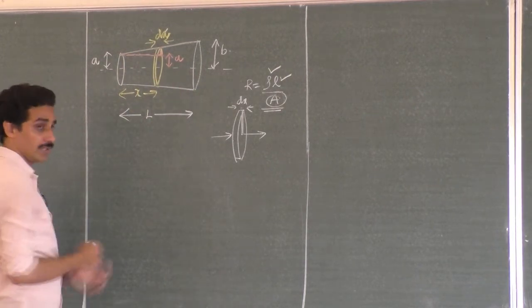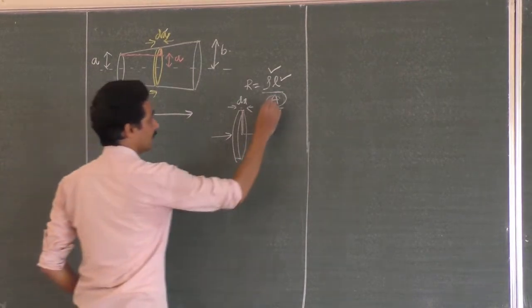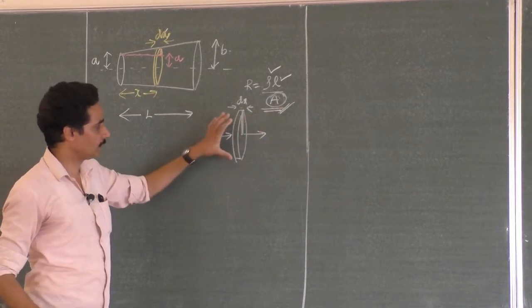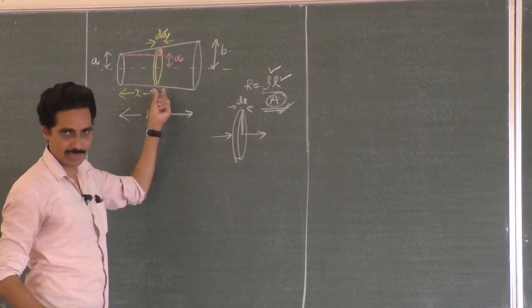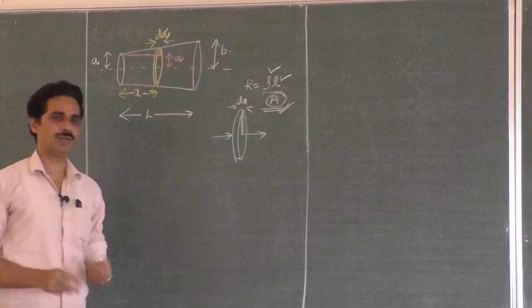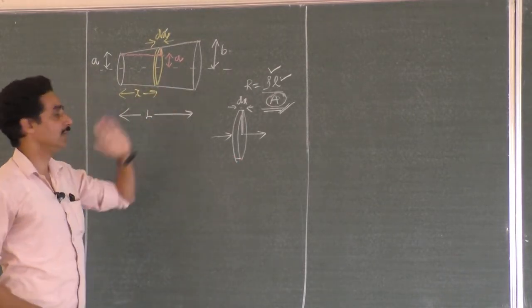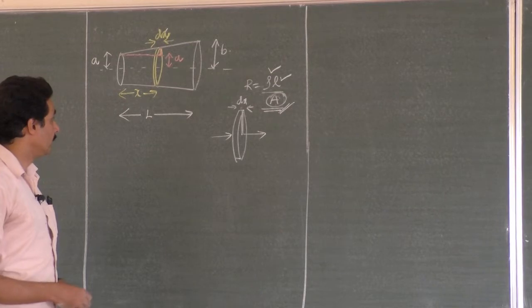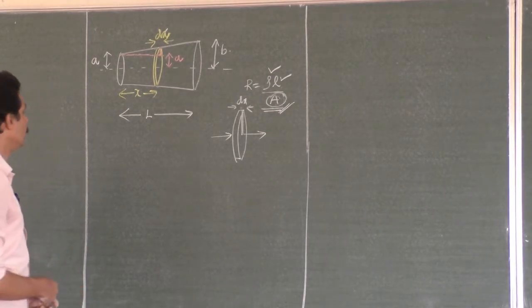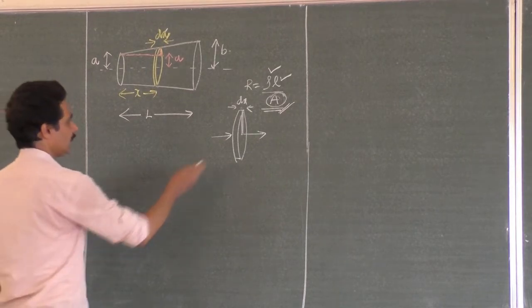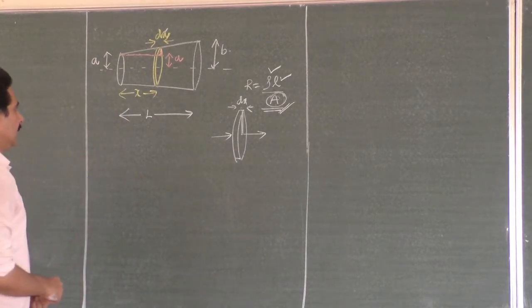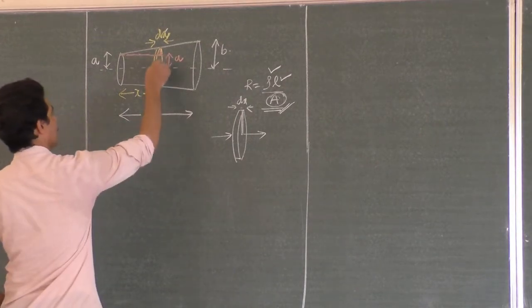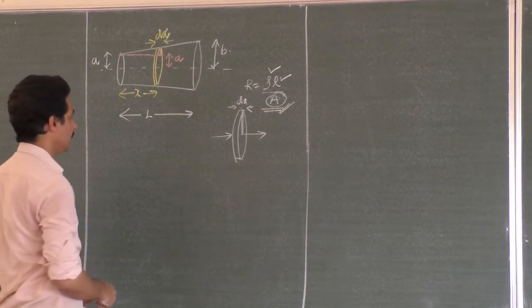Did you get that? Because we are trying to get the area here. If you get the area value, then you can write the resistance of the small piece of the material. Once you get the resistance of the small piece, you can integrate it from the left end, a, to the right end, b, and then continue. But in order to do that, we have taken this small piece. What is the radius of this? That is our question now. We have stopped at that point.